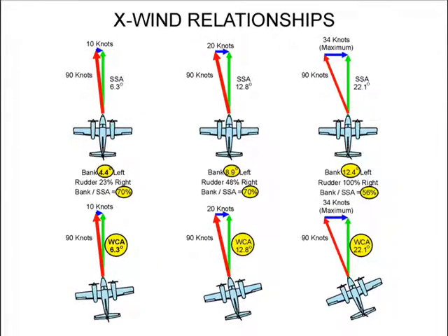Looking at these three examples, we see two important things. First, the given airplane at its approach speed has one exact slip bank angle for each crosswind. Second, this bank angle is slightly more than 1/2 of the crab wind correction angle. Now let's look at the precision transition in detail.